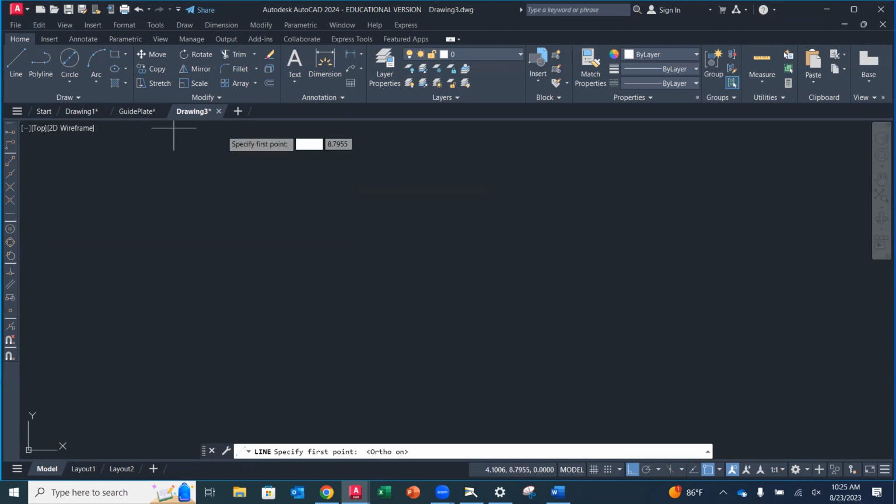That's what I want. So I have clicked on the line command, specify my first point. I'm just going to start right here, clicking. Now notice that I'm going to move to the right. Do you guys have this dimension up there above the line telling you how long it is? Okay, great. Everybody have that? All right. By having that, that's called dynamic input.